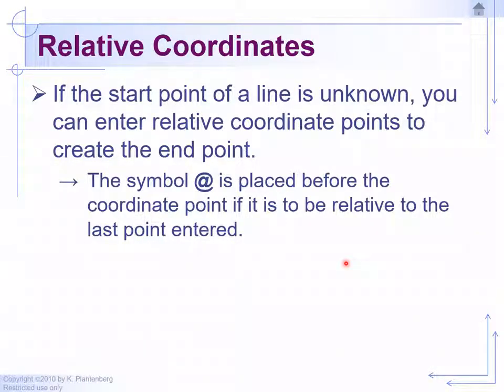Next slide. Relative coordinates. If the start point of a line is unknown, you can enter relative coordinate points to create the endpoint. The @ symbol is placed before the coordinate point, which is your xy, if it is to be relative to the last point entered. In other words, you want to define your endpoint with respect to the last point you defined and not the origin. Let's take a look at the next slide for a better explanation.